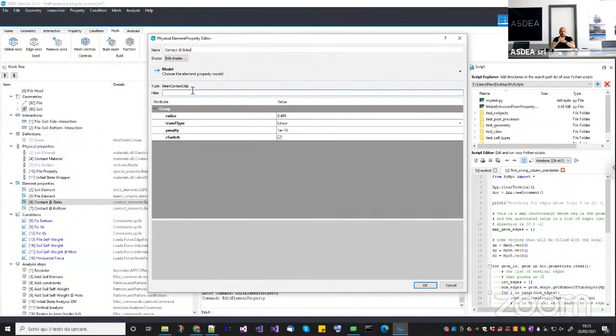Either the Lagrange multipliers, but the problem is that it requires extra degrees of freedom. That's why they need an extra Lagrange multiplier node. And working with Lagrange multipliers is quite a mess. So I decided to use the penalty approach. The penalty actually requires this extra parameter, the penalty parameter, which is actually a stiffness. And what is the meaning of this stiffness? Well, actually,